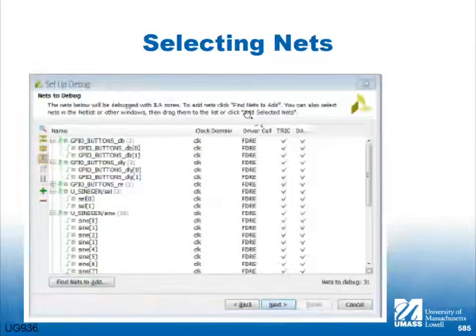Okay. Now, the important part, really important part, remember those 500 or whatever I said, 96 probes, I think, in that example. Every one of those, I had to connect to a certain spot. If I wanted to change them around, I had to change them around, and I was limited to pins on the chip. Here, I effectively have the net list of the chip available to me, and I can pick any one of those signals to be probed, right?